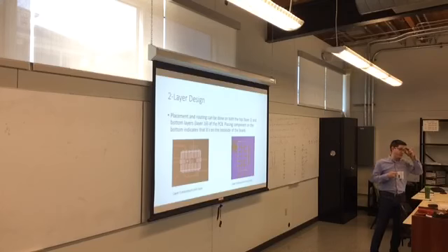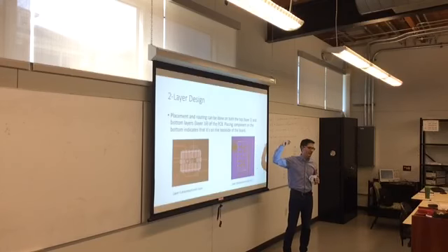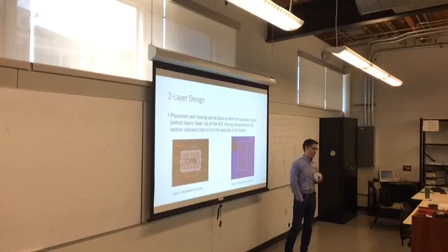So I'm just going to say it's a 2-layer board. There's layer 1, there's layer 2. But if you pulled up Eagle and wanted to show this layer, it's layer number 16. Just because 16 layers, layer 1 being on top, 16 being all the way on the outside of the board. So you just have no layers in between the 2. Yeah, it's just the 2.